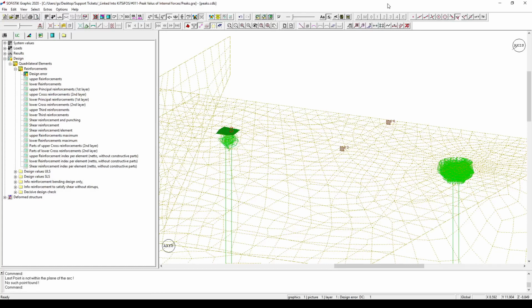In this case you need to go back and fine-tune the spring constant of the defined spring between the structural points. This is an iterative procedure and sometimes it is very time-consuming, but still better than the original layout when between the 2 structural points a rigid coupling was defined.